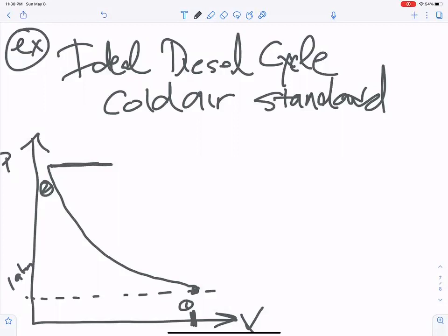And what the diesel cycle does in the ideal, simplified cold air standard case is you have this work in, isentropic. Instead of having an internal combustion engine where you increase the temperature, you have Q in as like a thermal heat reservoir at high temperature. The temperature increases, but the pressure stays constant because you are allowing this cylinder to expand to some extent. As the energy is coming in, the temperature increases, but the pressure does not, due to this increase in volume to accommodate that energy.